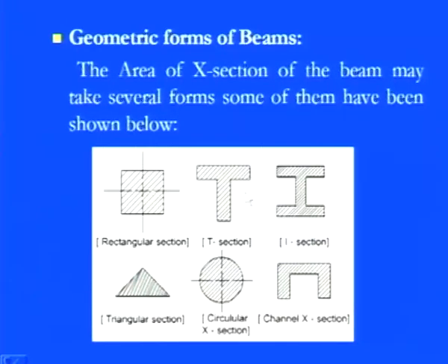So if you are designing a beam in which weight is the main criterion, the T section or the I section always gives you the minimum weight. But compared to the T section, the I section is more symmetrical, because you see here on the top and on the bottom we have a balanced shape, and in between there is a connection. With the T section, we don't have this particular part, so in some applications it gives you an imbalanced cross section.